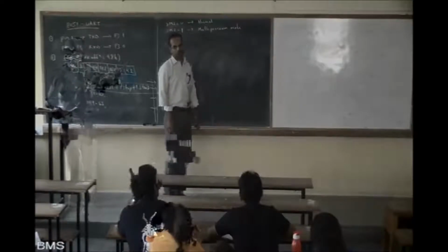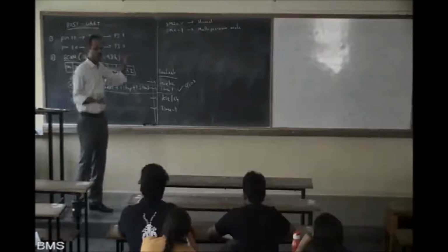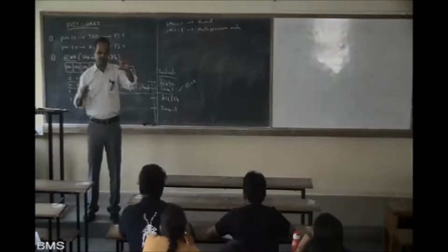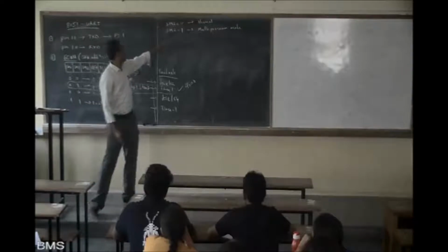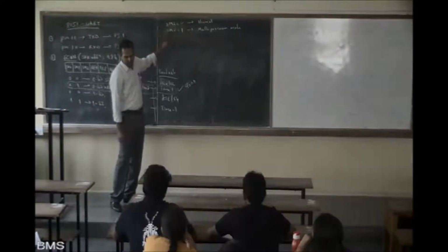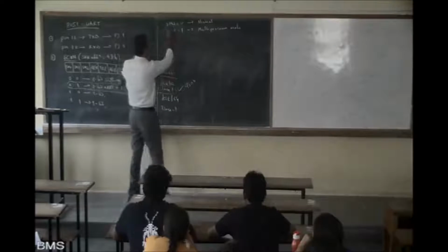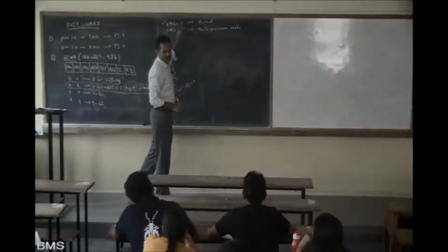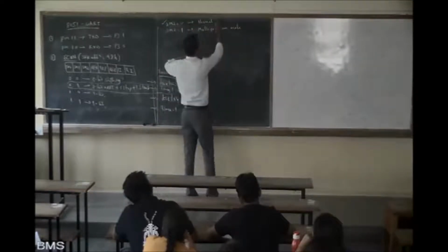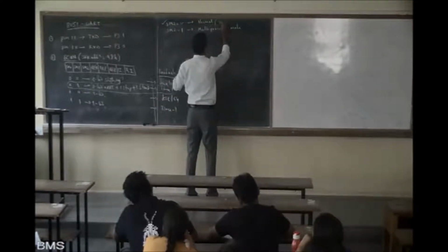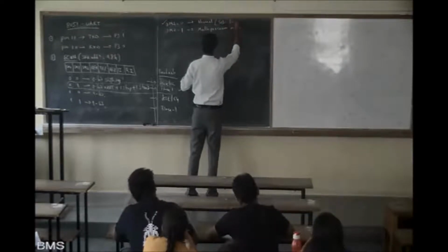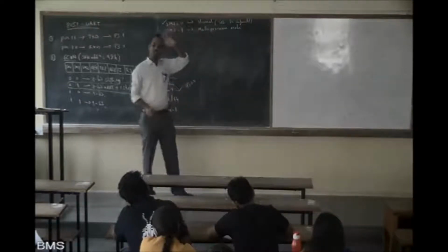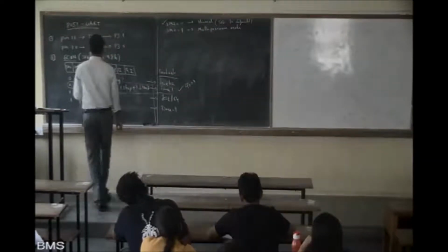Multiprocessor mode: 8051 connected to 8051, module 1, module 2, module 3. Then on the same cable you can use this. But again, this is not there in your syllabus. By default, SM2 is 0. This is the default condition. You can write here: set to default. By default, it will be 0, so keep it 0 only.